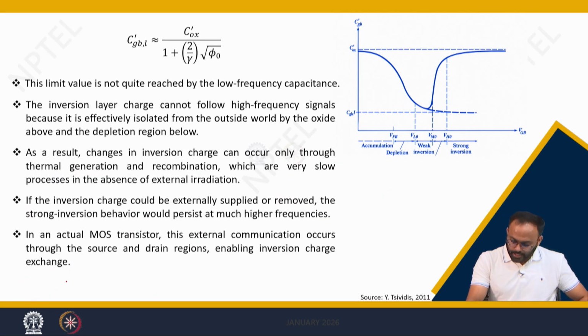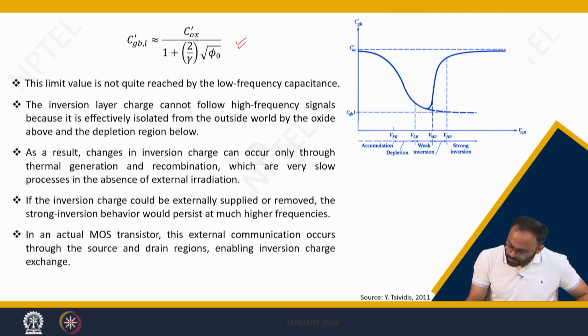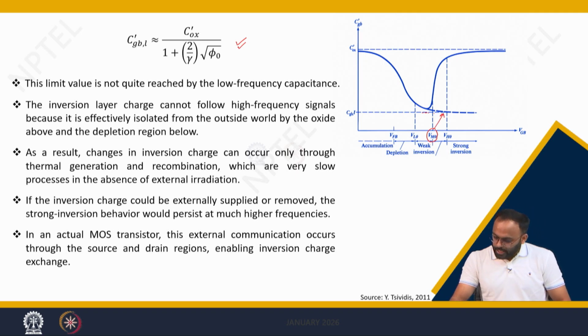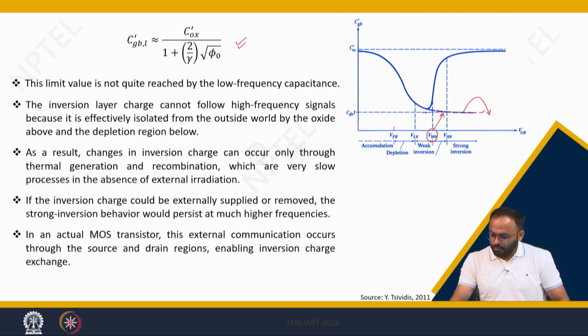So, this is the final expression we got for the 2 terminal MOS cap, which says that the minimum capacitance exists after this VMO point, because we claim that after this VMO point we will go in strong inversion. Let me conclude this CV characteristic with one more additional point, that this dotted line shows the CV curve for high frequency of operation.